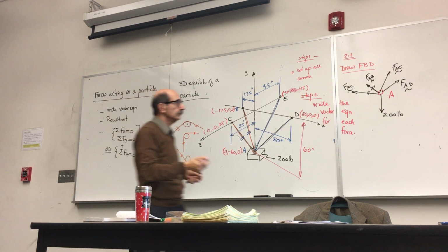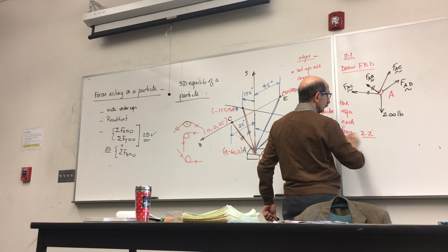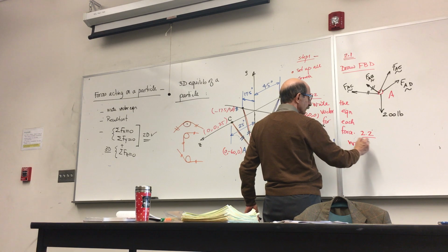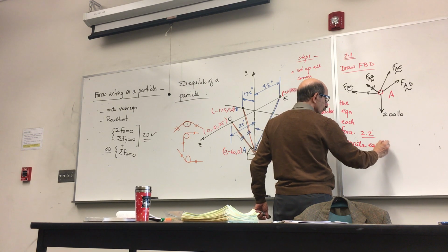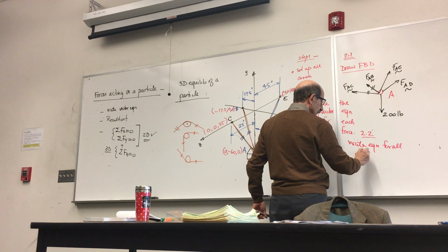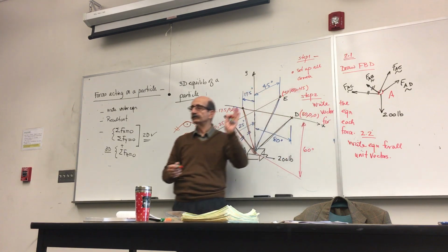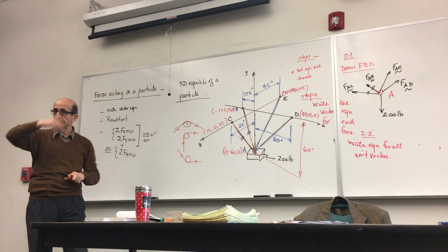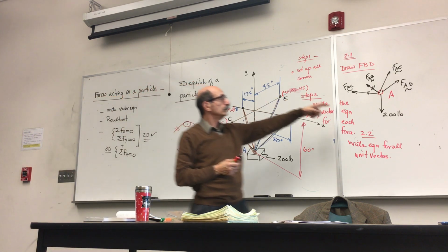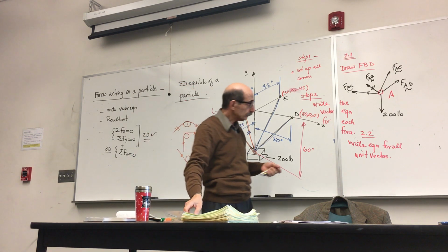Once you've done that, then step or sub-step number 2 is you would write the equation for all unit vectors, meaning the unit vectors that are along the direction of each force and define the direction of those forces. How many forces do you have? 1, 2, 3, 4, 5. So you need to write all 5 unit vectors.